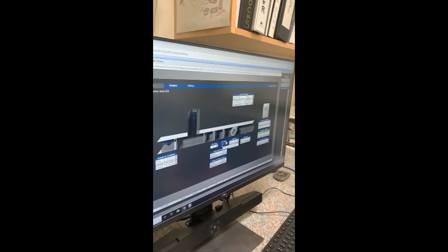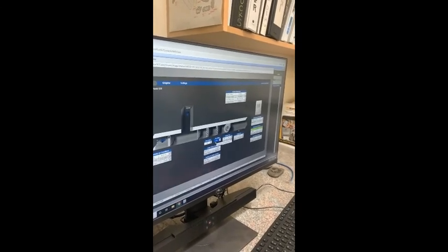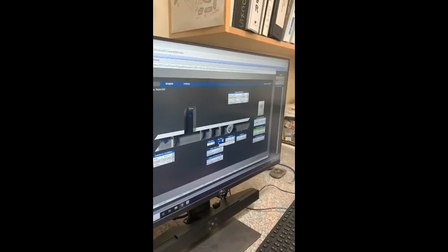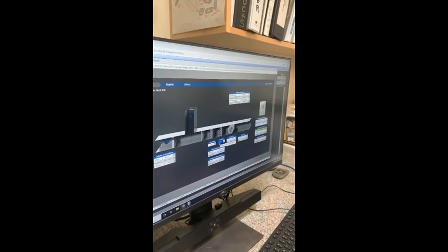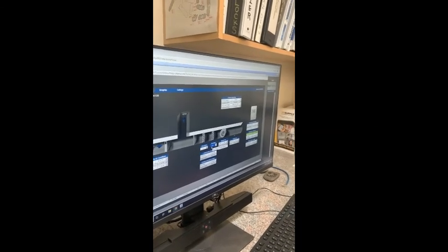I assume it's just a straight-up spec'd 0 to 10 volt DC valve, and all they know is they're just getting this low voltage input. If it was entirely up to me, I would always put valves with feedback and actuators with feedback. It's a lot more expensive. And there are no water flow meters in each individual fan coil, so we don't know if strainers are clogged or not?